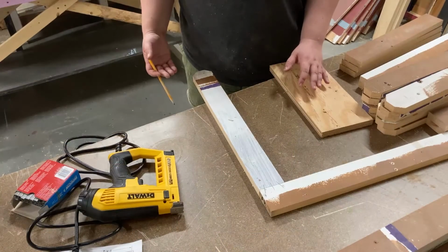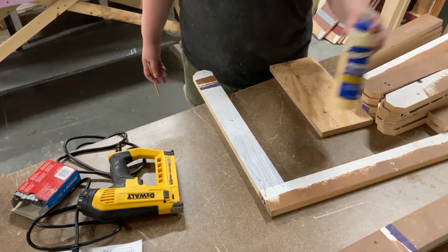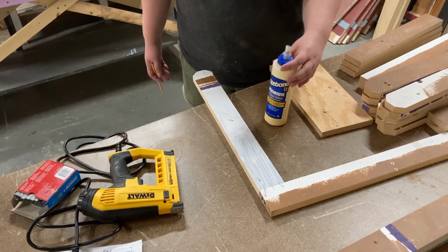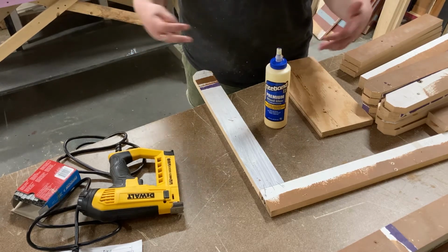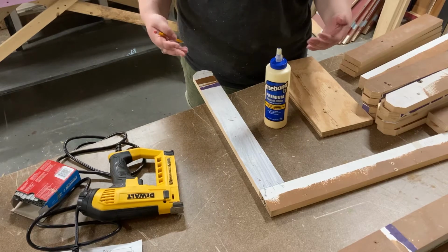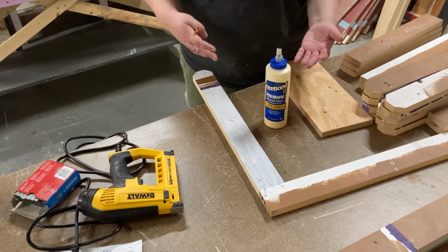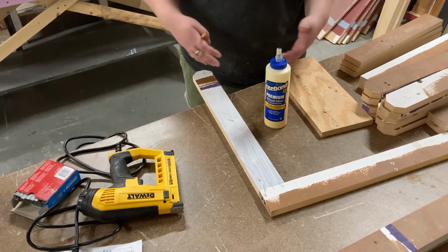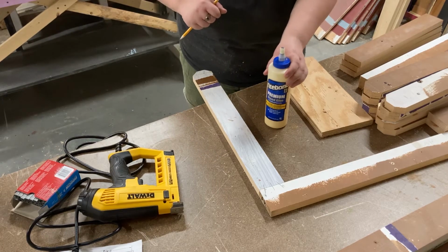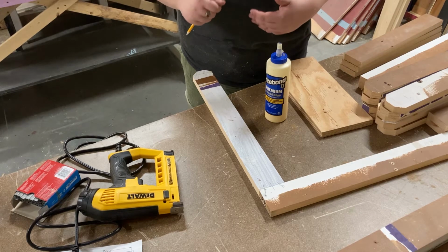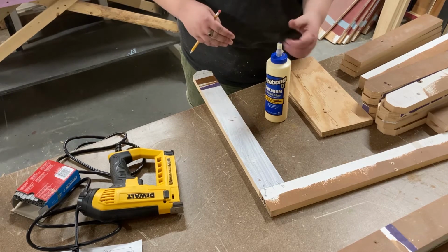On a flat frame like this, your wood glue is actually providing all the strength in the joints. We're going to be using staples as a way of sort of knitting together the pieces long enough for the glue to set up and create a very strong bond. Once it dries, oftentimes you'll find that if you try to rip apart two pieces that have been bonded with wood glue, the wood itself will start to tear before the glue will fail.